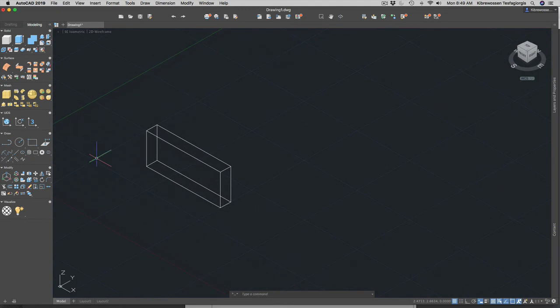Now let's go ahead and create a cylinder. There is a function called cylinder in AutoCAD. Then you have to enter the cylinder coordinate, 5 point, it's the center, of course. So 5, 3.75, 1.5. That's where the center of the cylinder is.